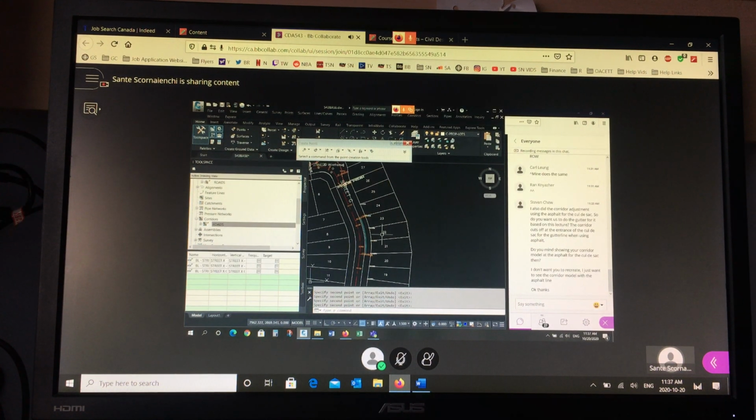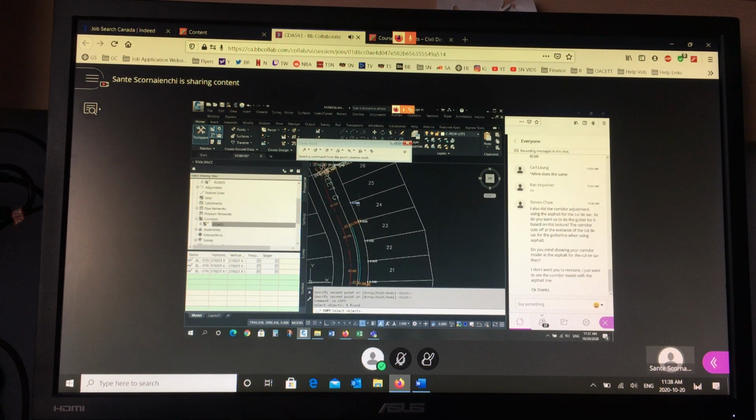You remember we had different groups with different layers? We're going to do the exact same here. So I need a layer for the front lot corners, that's the proposed elevation. I need a layer for the rear lot corners, that's the existing elevation. And I need a group for each, because you're going to have a different style for each. So you put elevations at the front, you put elevations at the back, same technique. You put points at the back.